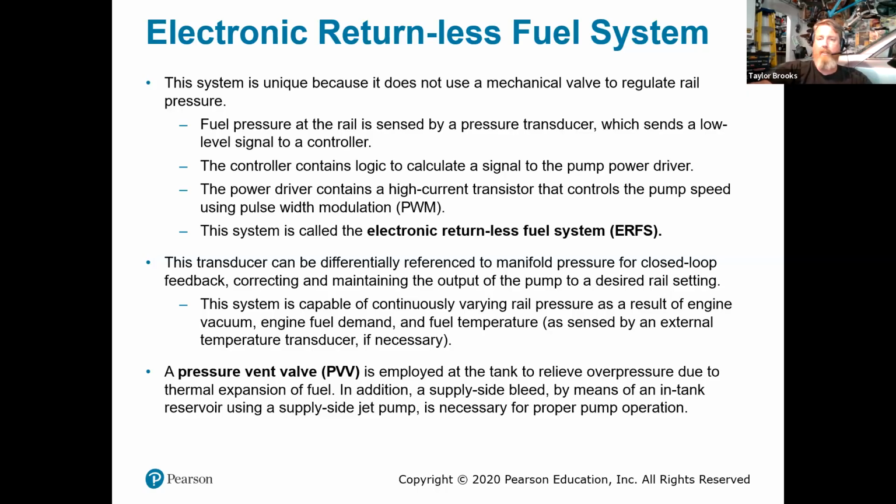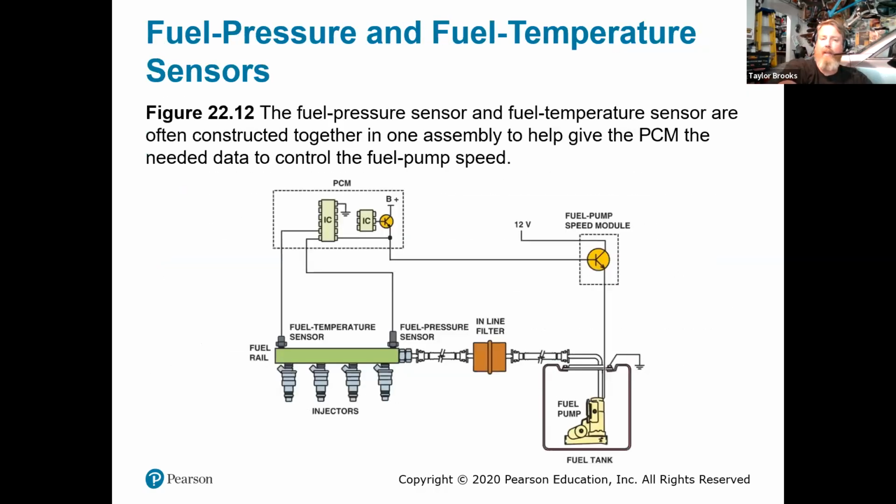Now, the benefit to this is we're reducing components, which reduces ultimate cost, and we're simplifying the fuel supply system. But it doesn't have the benefit of cooling everything down like it once did. So there is that little bit of a drawback, but the cost benefit, as well as the ability for the fuel system to be pretty consistent, is high.